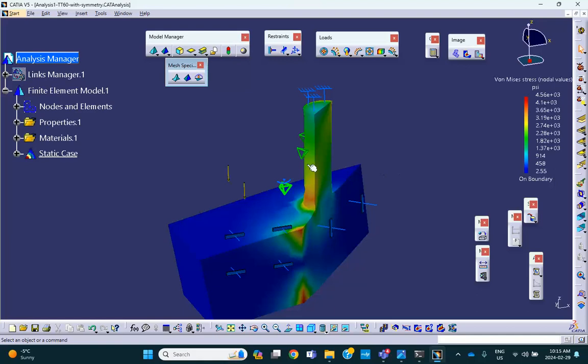One other comment is that notice that when I meshed the original model, the size of the mesh before I did the refinement was much bigger than this, because Catia has an algorithm which looks at the size of the object and based on that comes up with the original mesh size. Here, because the size is only 1/8 of the original one, this is actually smaller than what you saw originally. And that's why when I did the local mesh size, 0.3, it doesn't show much smaller than this. Anyway, that takes care of this activity.